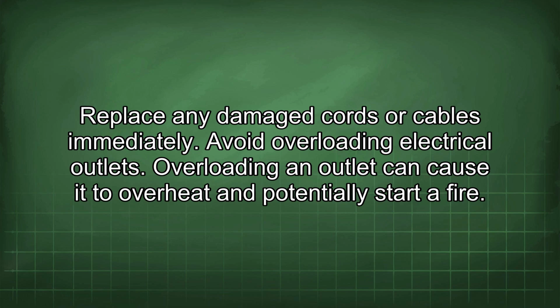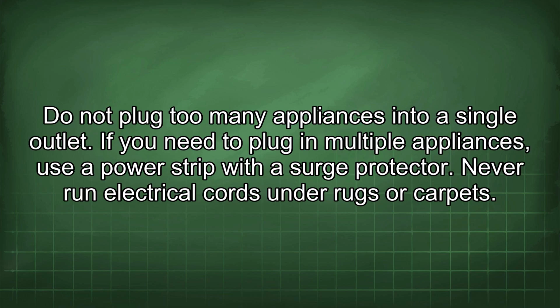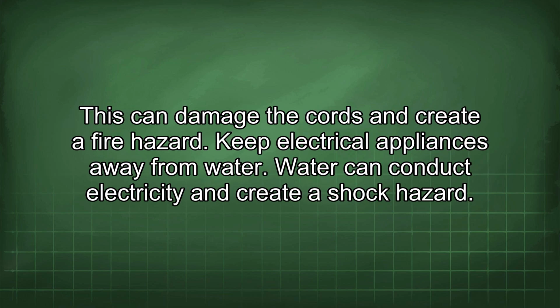Avoid overloading electrical outlets. Overloading an outlet can cause it to overheat and potentially start a fire. Do not plug too many appliances into a single outlet. If you need to plug in multiple appliances, use a power strip with a surge protector. Never run electrical cords under rugs or carpets. This can damage the cords and create a fire hazard.